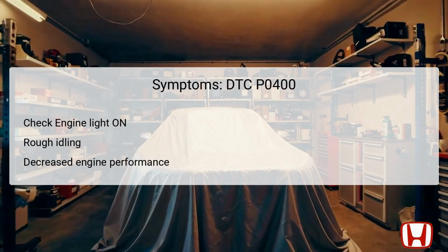Symptoms associated with DTC P0400 typically start with the illumination of the check engine light. This is a warning that the vehicle's computer has detected an issue with the EGR system. Additionally, you may notice rough idling where the engine does not run smoothly when at a standstill. This may be due to irregular combustion caused by insufficient EGR flow.